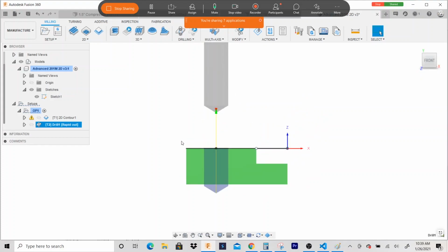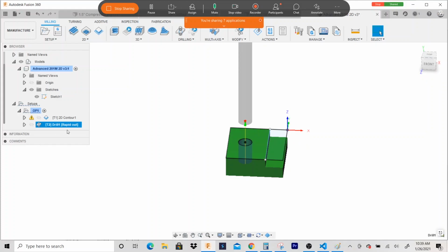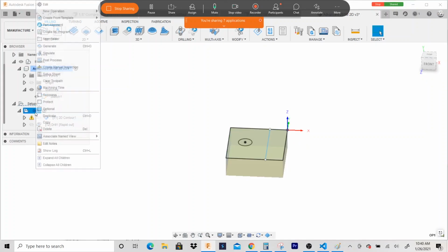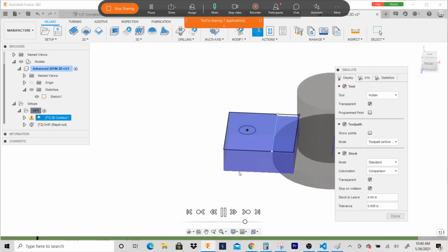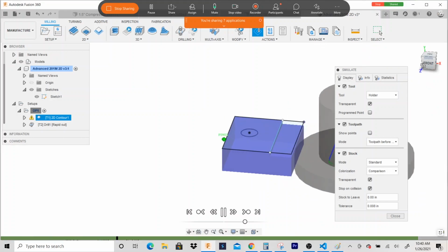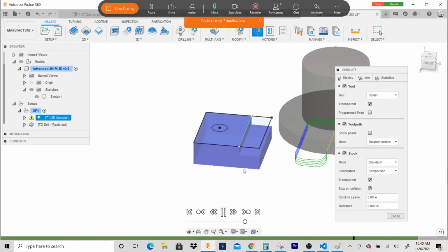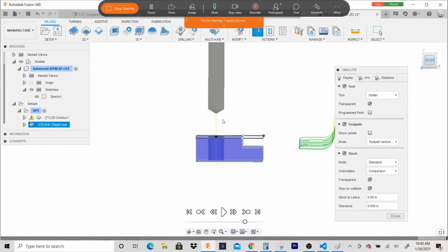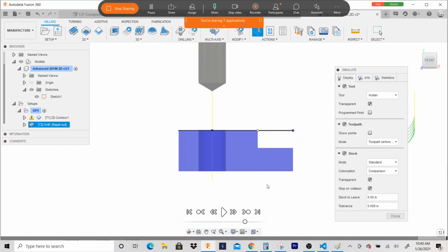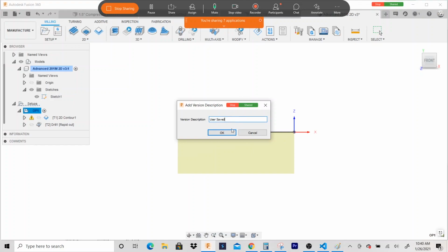Okay, so on this example, I'm just going to drill the hole because that would totally work on this part. You don't actually have to get an end mill involved, but it would look something like this. So you come in, face it, and you come in and drill it. You want to make sure the body of the drill is going through the stock. Alright, so that's that.